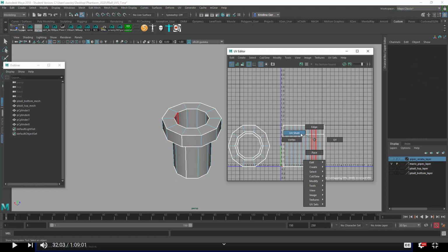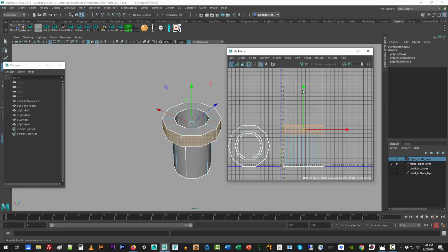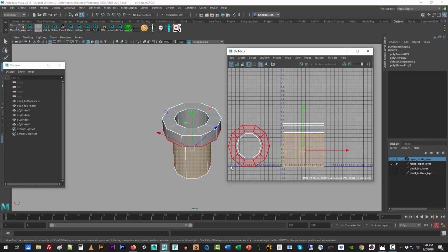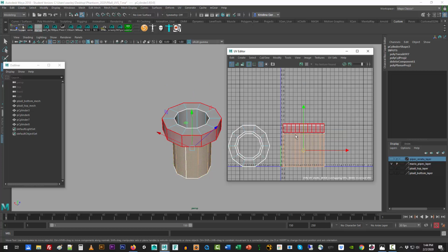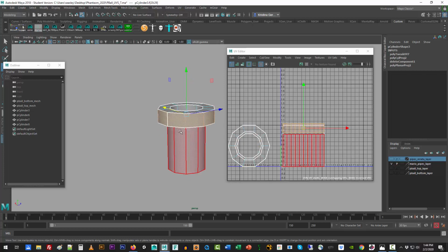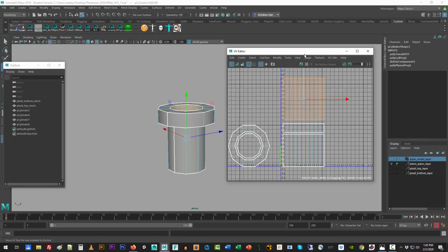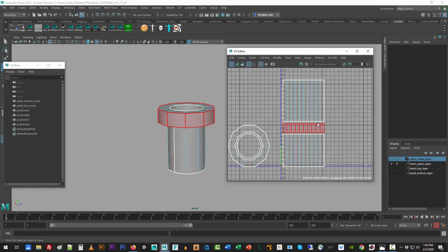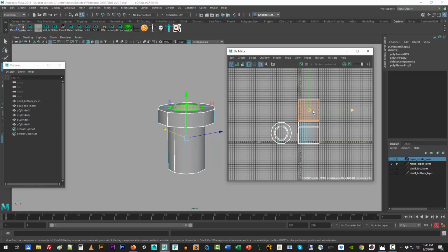And the best way to do that is to go into UV shell selection mode and just kind of separate things out. And the way I'm going to separate them is I'm going to grab the outside and put it at the bottom. Here's my progression: outside, the ring here, then inside. It's arranged quickly thus. And since I'm in UV shell selection mode, I'm able to kind of dance quickly through these different selections, either in the modeling window or the UV window. So I've sorted these things out. These are kind of complete. In fact, I can scale them, just make them a little bit shorter.